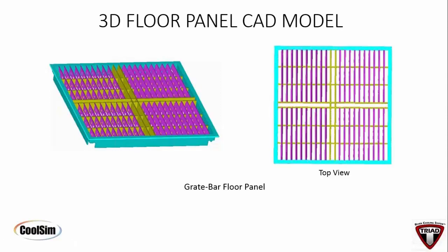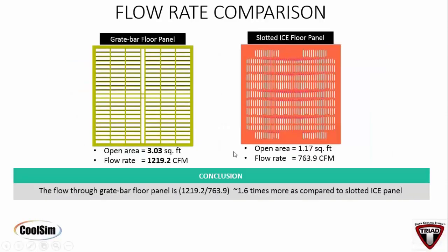Again, I get back to this issue of dynamic pressure versus static pressure. If there's any movement of air under that floor, and of course there is movement because it has to come from the cooling unit out of the floor, so it has to travel across the underfloor. If that velocity component moves up at all, for example, you've got a shallow underfloor. I see many underfloors 18 inches, even 24 inches. I've seen them 12 inches. I've seen them, Gary, as low as 6-inch floors, and people trying to use them for raised floors. So you have any of that horizontal component, this thing breaks down and doesn't behave itself correctly.